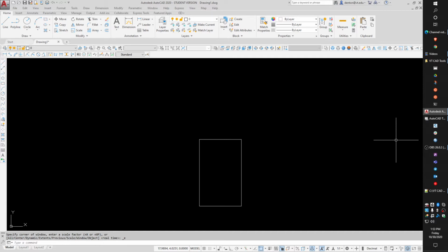There's really no end to the customization you might want to do. One of the things that I don't like about AutoCAD is I think their arrow command is really bad. What they have is called a leader. Leader, leader, and you pick where it starts, you pick where the text should go, enter for annotation, and you type your text in: A, B, C, enter, one more enter.